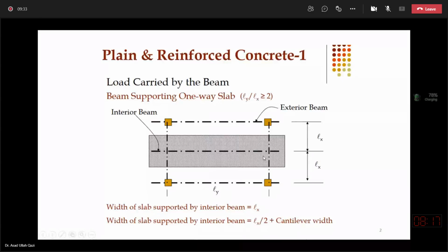So it seems that there are two panels now which are resting on these beams on the perimeter, and if we measure the dimension center to center of the beams which are running on column center lines, or this secondary beam which is dividing the center to center distance of column exactly into two sub panels, that dimension is then L with subscript X. So this is actually the dimension center to center of the two parallel beams, and it is the shorter dimension of this one panel, and the longer dimension of this panel is L with subscript Y. So there are two panels and their dimensions are Ly into Lx.